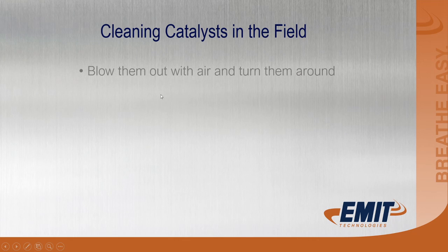Cleaning catalysts in the field, your best bet is to blow them out with air. It works more times than not. The things it won't work on are obviously oil, it won't work on carbon, and it won't work on antifreeze.